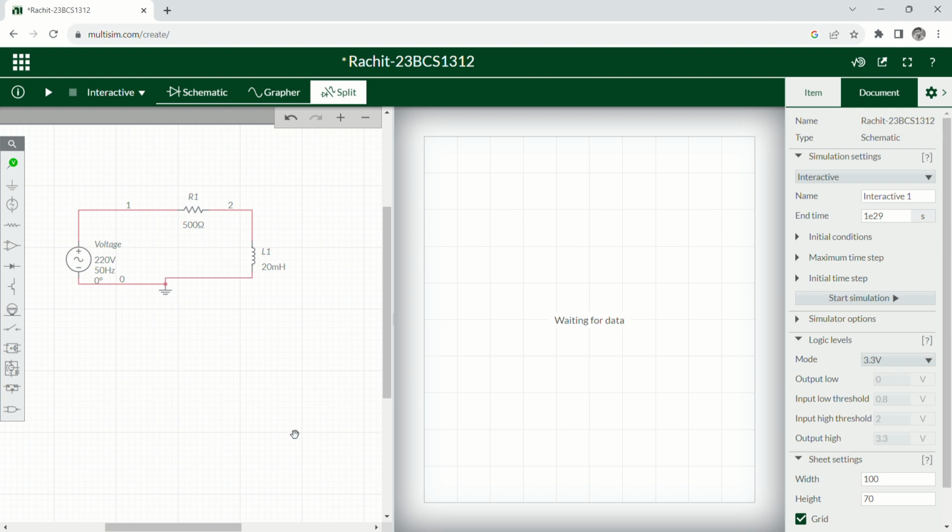Okay, so here the value of the resistance is a bit high as compared to the inductor. In this particular scenario, the overall circuit is going to show me the resistive behavior. So that means the voltage and current which I'm going to see here on the graph are going to be in the same phase because the resistance value is a bit high. That's why you need to take a different value of the resistance after this, where we can show the circuit's inductive behavior. That part comes later. Let's stick to this part.